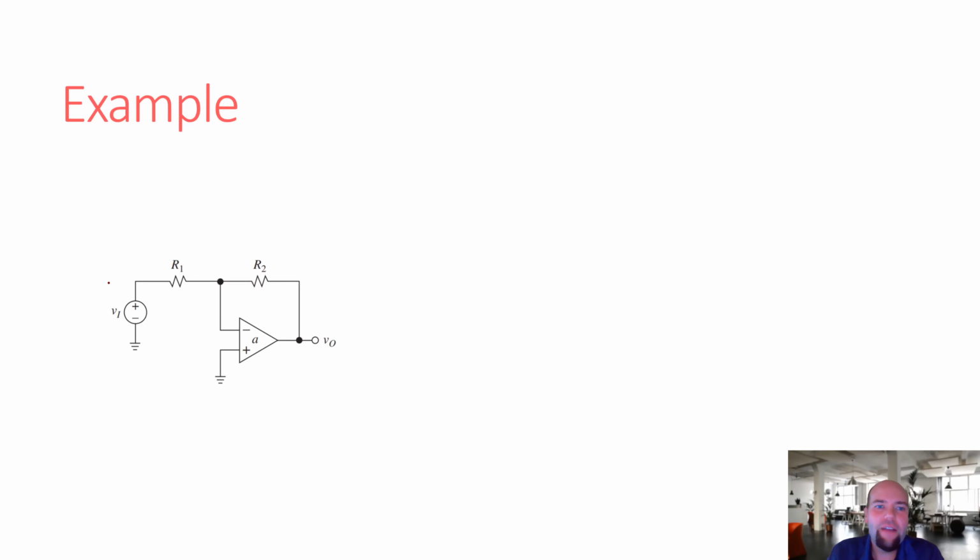This is the non-inverting amplifier. The positive terminal is grounded. Terminals stay at 0 volts, no matter what the input voltage is. So that should cause us to go, okay, I wiggle my input, the input terminals of the op amp don't change, which means probably what's happening is I'm converting this input to a current, and I am actually doing an input combination in shunt. So by our wiggle the input test, this is actually a shunt input.